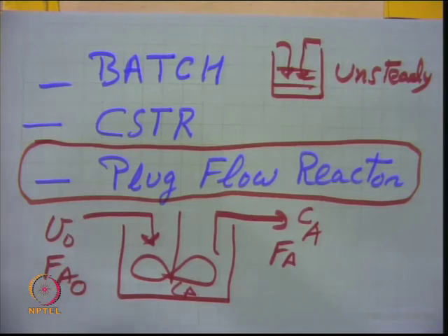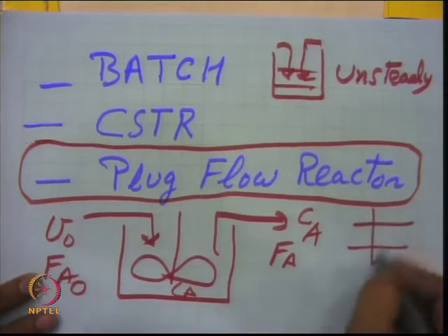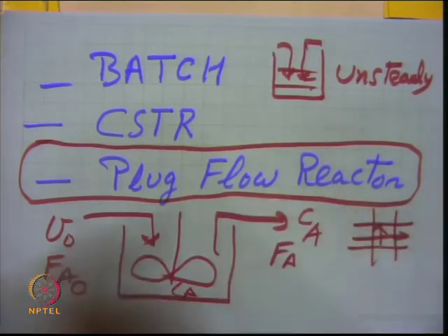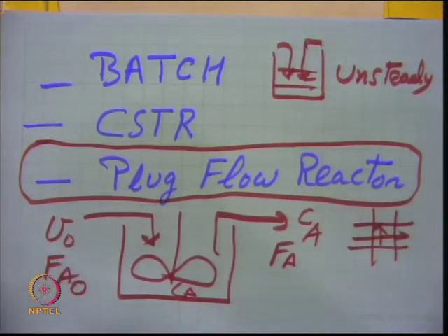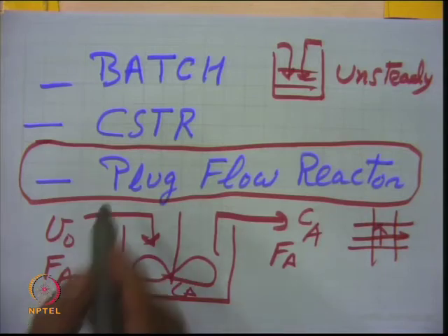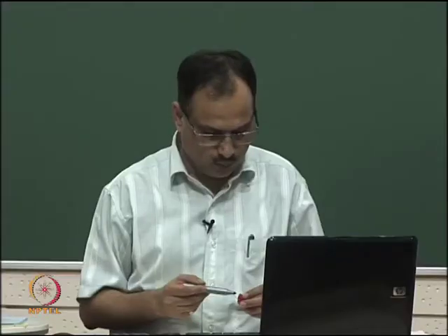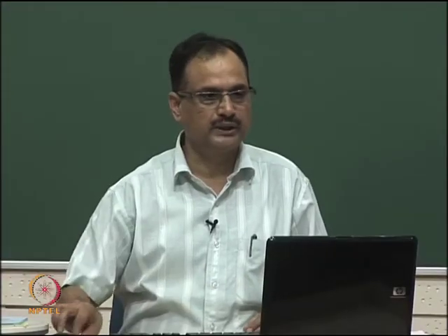So, plug flow is generally an ideal condition of reactor where the dispersion, axial and radial, is neglected. Basically that is the ideal reactor condition, but the definition says that there is complete mixing in the cross section and no mixing in the direction of flow, right. The concentration, if you look at any section, is uniform throughout, right. So, it is the most idealistic form of reactor, and since this can be sized in the form of tubes, most of the commercial industry uses this kind of reactor.